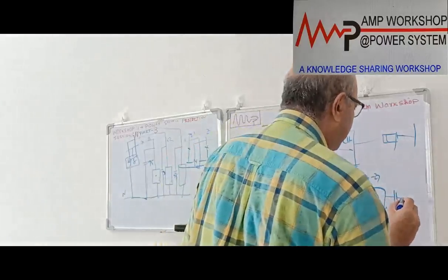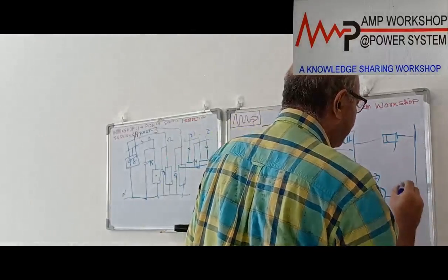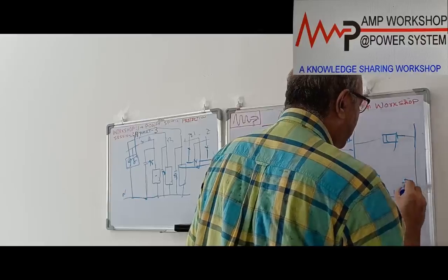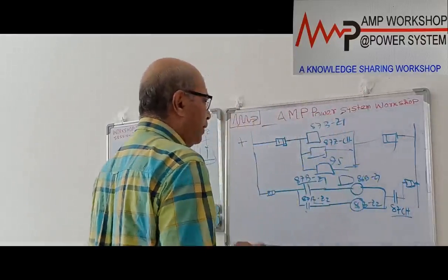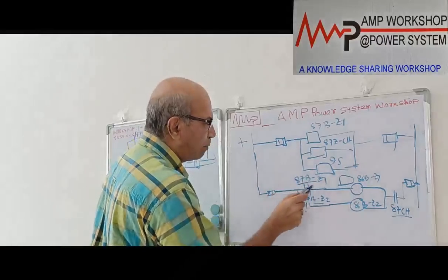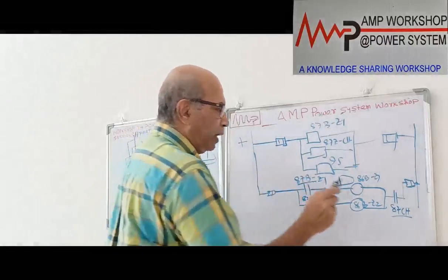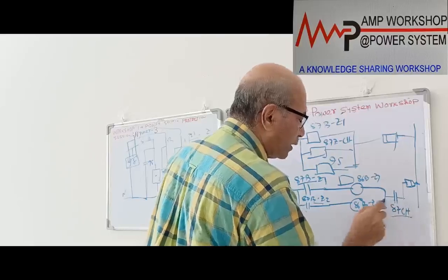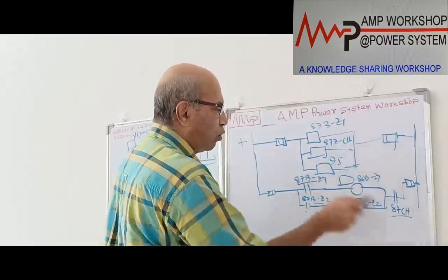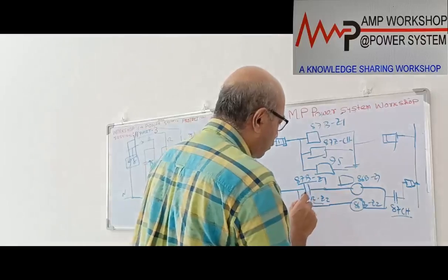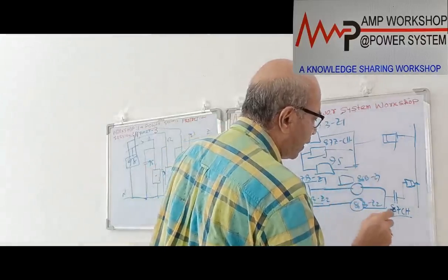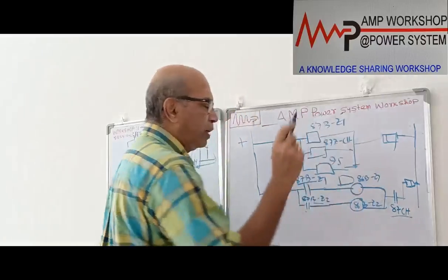So this will come to the negative bus through the fuse, connected to the negative. So what will happen? The moment the zone 1 differential relay operates, and if both the backup protection and the main protection of zone 1 operated, then immediately this contact will be NC, then 86B1 is operated, then a lockout relay is operated.